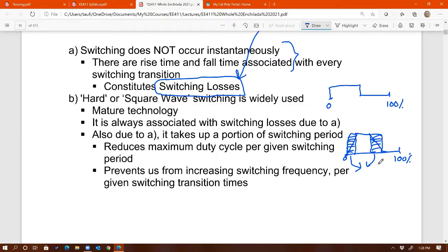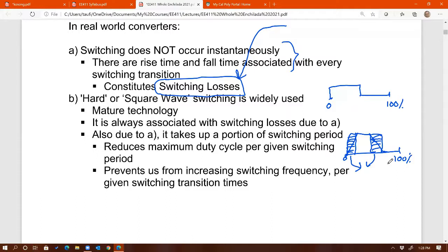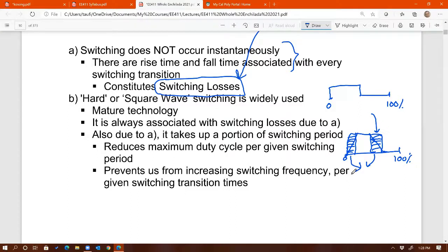Same thing with the 95%. If your maximum duty cycle, you calculate it to be 96%, change the design because that's not going to happen. It's going to be hard for the converter to regulate the output voltage if the max duty cycle is 96%. It doesn't have any more margin to go over 96%. Remember, you have to allow the switch to turn off, right, or on. It takes time for them to turn on and off. Okay. Any question on that?